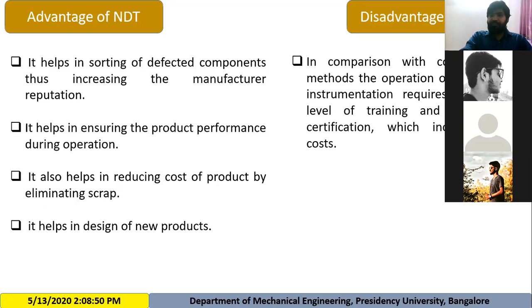Coming to the disadvantage of non-destructive testing, the only disadvantage associated with this is, in comparison with conventional methods, the operation of advanced instrumentation requires a higher level of training and additional certification, which incurs more cost. In a very simple way, what it means is that you require very highly skilled labor or a very highly skilled trainer in order to perform non-destructive testing. It cannot be performed by a semi-skilled operator.